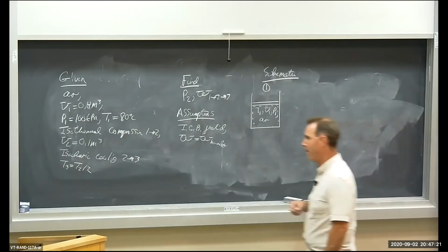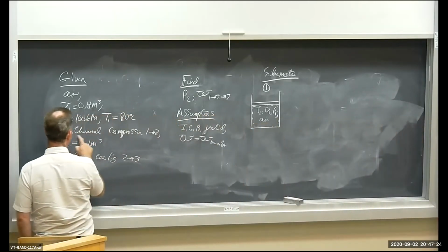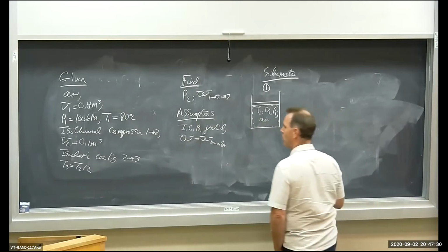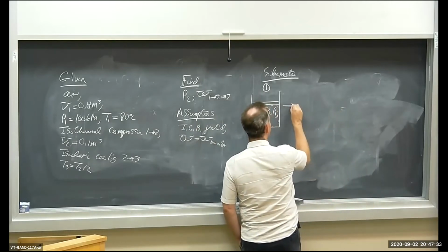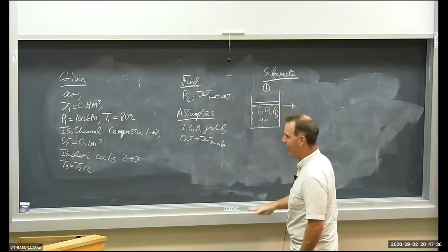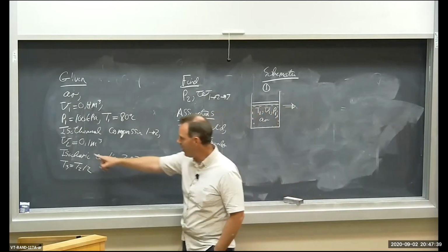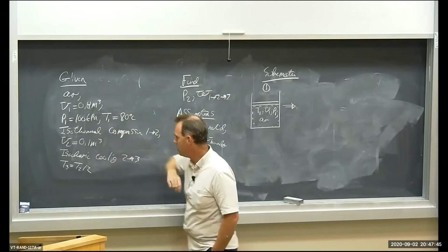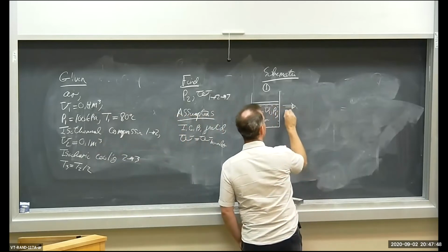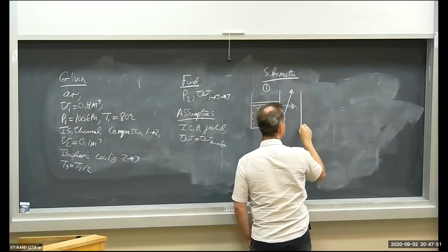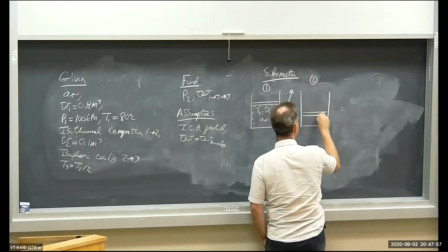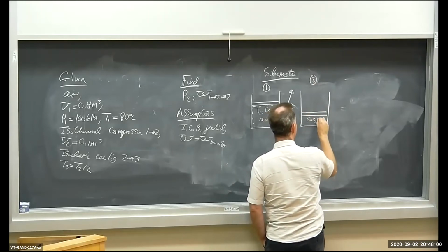That's good. And then we undergo isothermal compression. Isothermal means constant temperature. Isothermal compression to state 2. So we compress the gas down, and we end up at a volume V2 of 0.1 cubic meters. So we go from 0.4 to 0.1 cubic meters. So here is state 2. And now we've squeezed down the piston. So here I have our gas, and I have a volume V2, and a temperature T2, all sorts of stuff, okay?